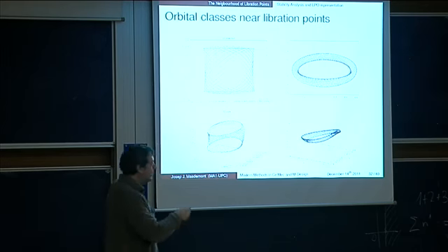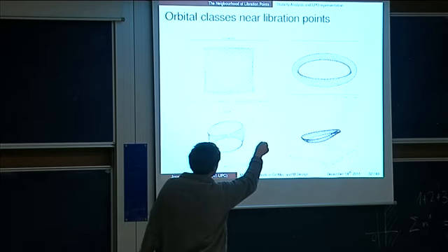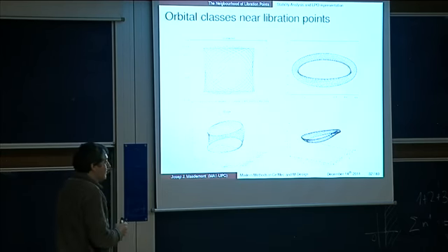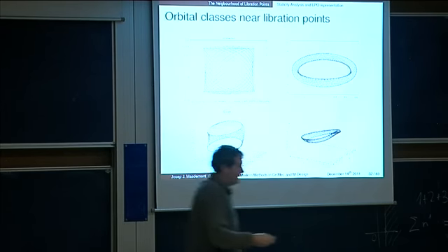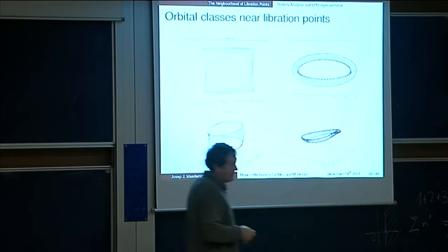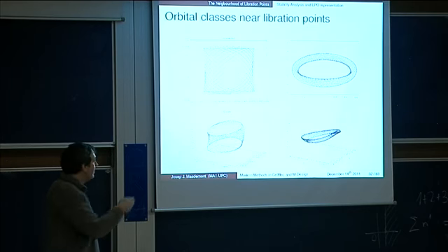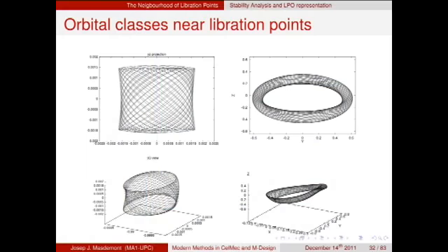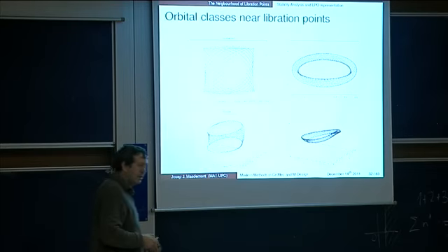Okay, these have nice properties. This one has the property that when we put the sun in the picture, the sun will be, say, in the center. So these orbits avoid the sun. To avoid the sun is very good because the radiation of the sun hides the signal from the spacecraft. So it's important to avoid a zone about the sun, and these orbits do this job. But these ones don't do this job because at some point the Lissajous orbit will cross the solar disk.